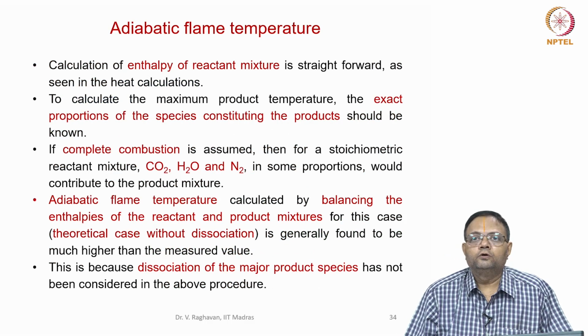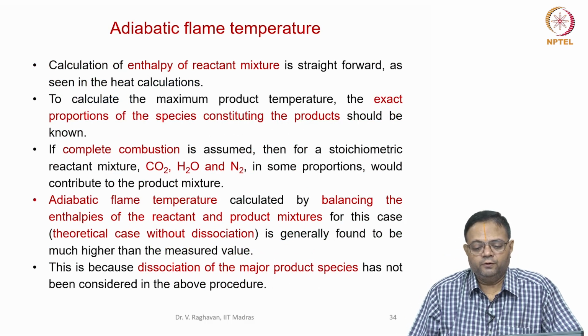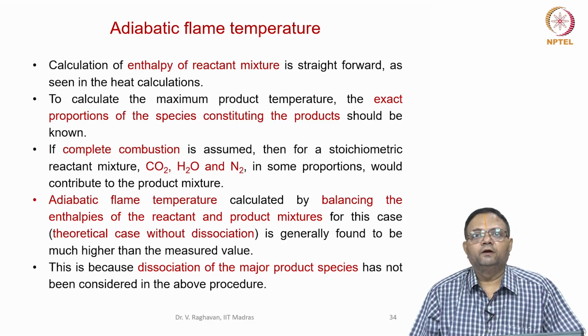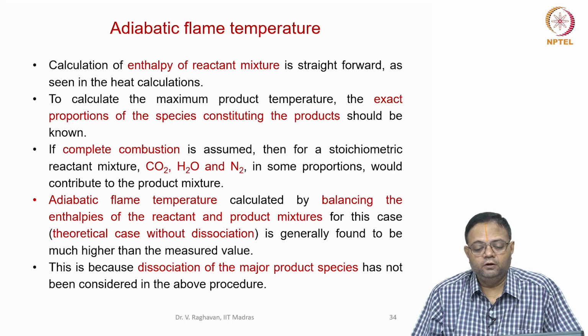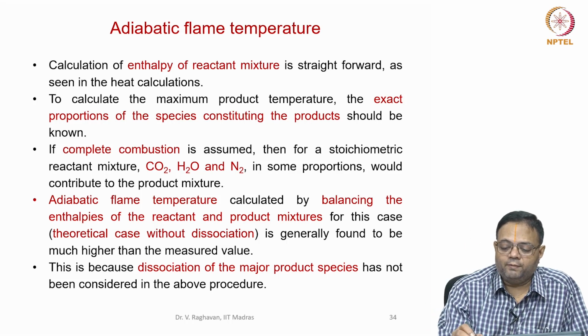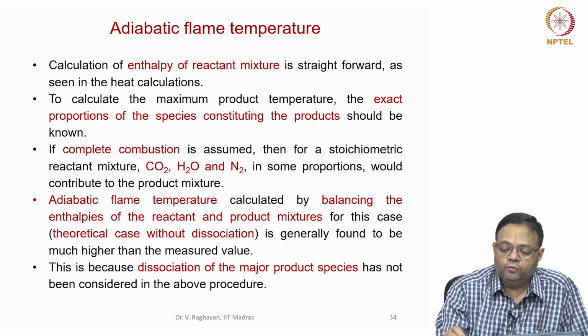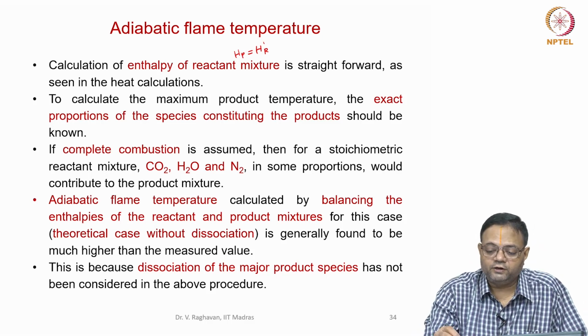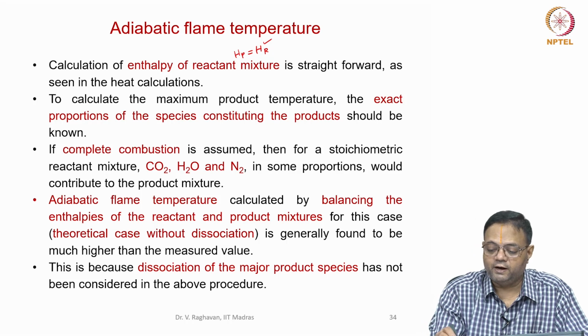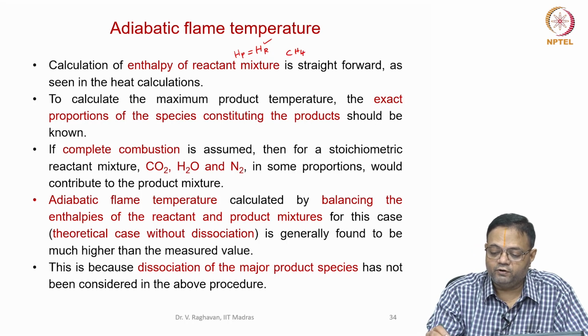Now, let us consider the calculation procedure for the adiabatic flame temperature. Adiabatic flame temperature can be calculated with this condition that Hp is equal to Hr. Calculation of Hr is straightforward. So, consider a reaction, say methane itself, for example.